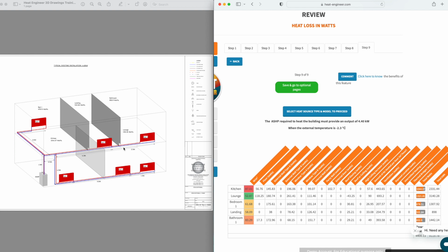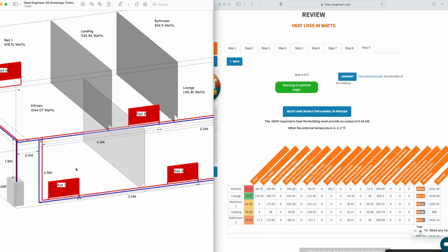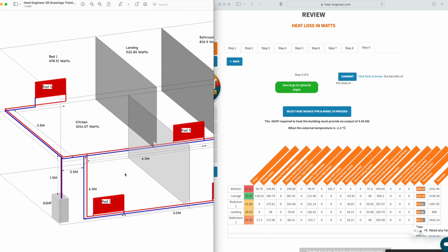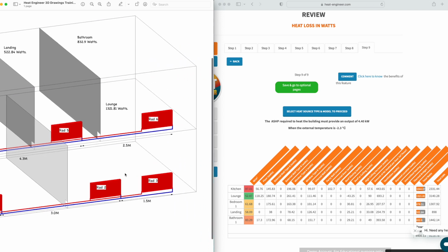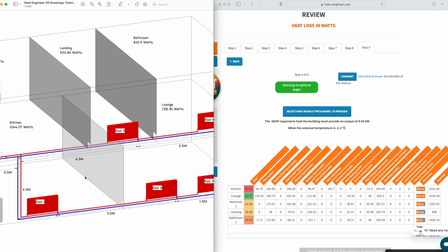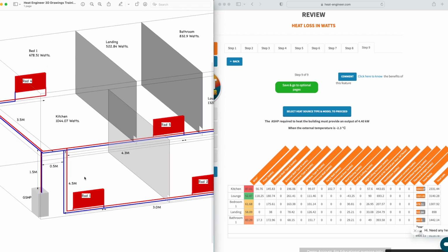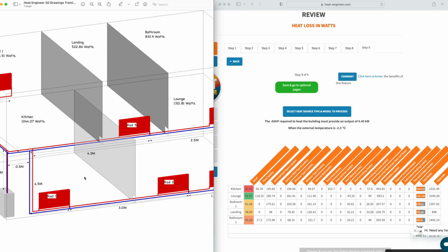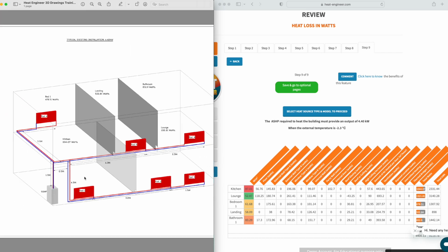Now you can do one or two things. This could either be an existing system that you've drawn out, or you could design it from new. It's entirely up to you how you want to work this, and we'll discuss both ways of doing it. This is whether it has microbore in a section there or whatever we've got. If I zoom into this drawing here, you don't have to do any drawing as neat as this. The only reason I've done a drawing like this is so that it's easier for me to explain the methodology behind calculating index circuits and obviously your pump sizing, or fundamental pump sizing, for all your pipework, etc.